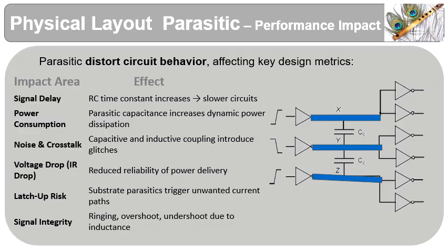Physical layout design has a direct impact on circuit performance, as it defines the placement and routing of devices that adds unavoidable parasitics. The parasitics from material properties, device structure, and proximity effects can lead to multiple performance challenges. Signal delay occurs due to increased resistance and capacitance of interconnects that slows down the signal transitions and degrades timing closure.